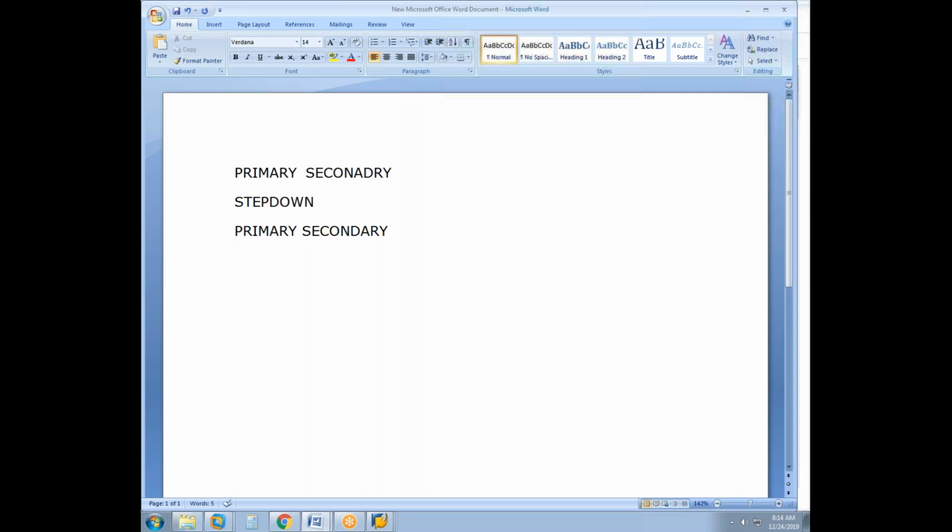So you can have one more winding as a secondary winding, which will act as a protective winding. That means one secondary winding is connected for the measurement, and one more secondary winding would be there as a protective winding. Okay. So all this information we gather through the winding group.